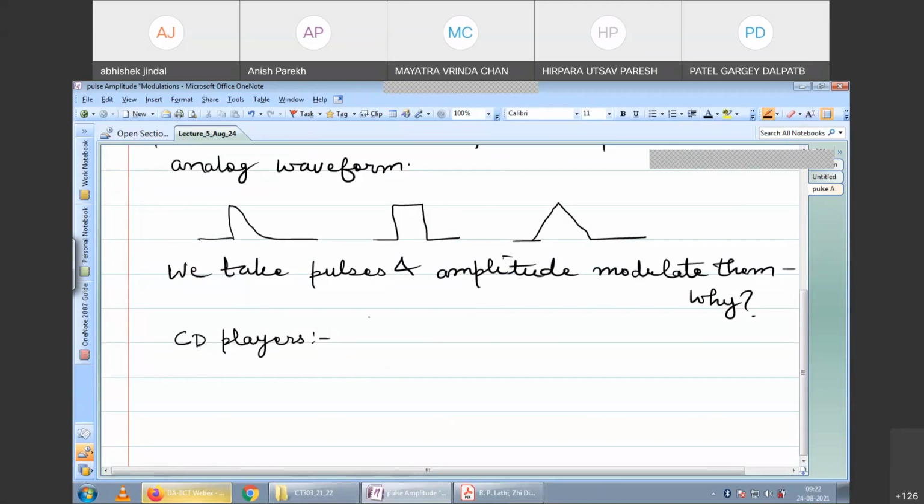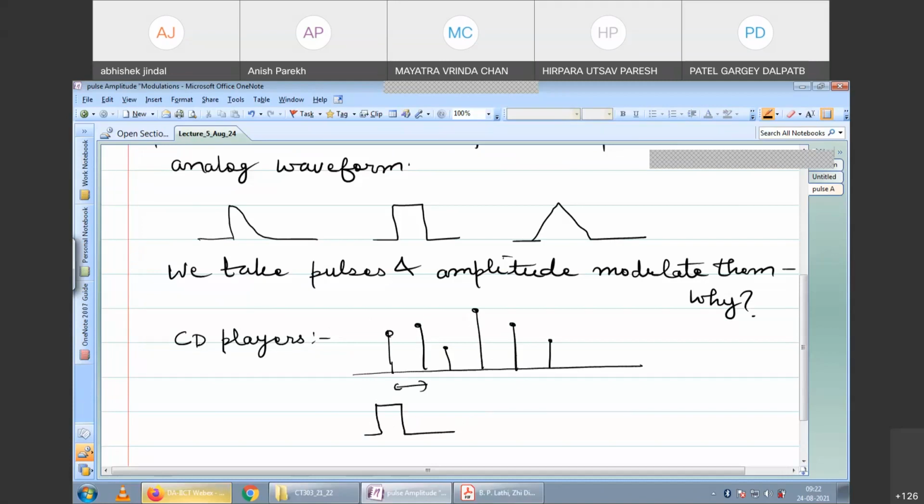So what you do is you say that if my samples are coming like this, let us say my samples are taking these values as a function of time, discrete samples which I have stored. Why not, since I have this much of a gap in between, take some sort of a small pulse and capture the amplitudes in this pulse, and generate a continuous time signal?